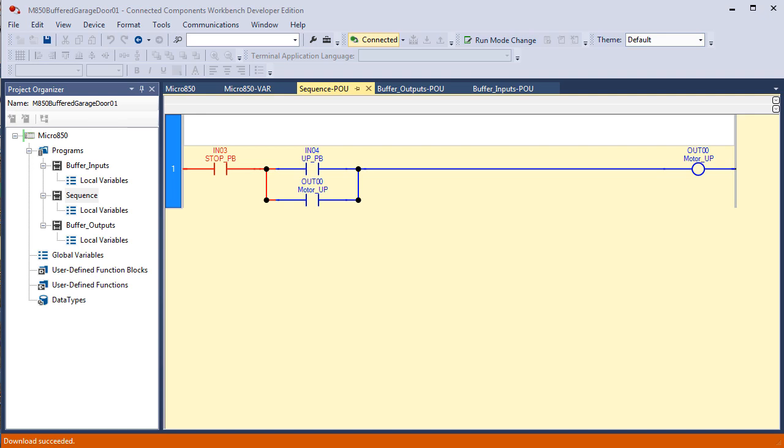If I momentarily push the input button, which is input 4, and I hold it down so you can see it turn red, then release it, you see it's false, you see it seals in, because once we have the motor running, when you're scanning the logic, it reads the stop push button is on. It's not pushed, therefore it's on.